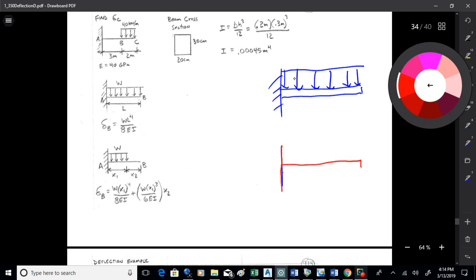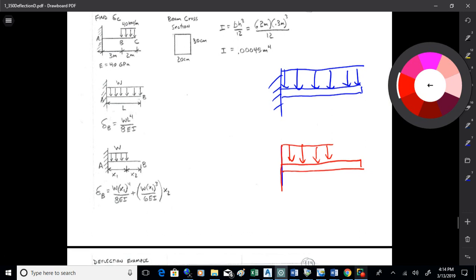So if I have that cantilever beam with a load over some part of the beginning, I've got a table that'll give me delta for that. But I don't have a table for my particular situation. So what I can do with this is I can take that top table, figure up delta for it, and then come in and figure up delta for the red loading there on the bottom, the partial loading. And what am I going to do with that partial loading? Subtract it, yeah. See, so sometimes you have to use these tables kind of creatively to get to what you want, okay? So that's one example.